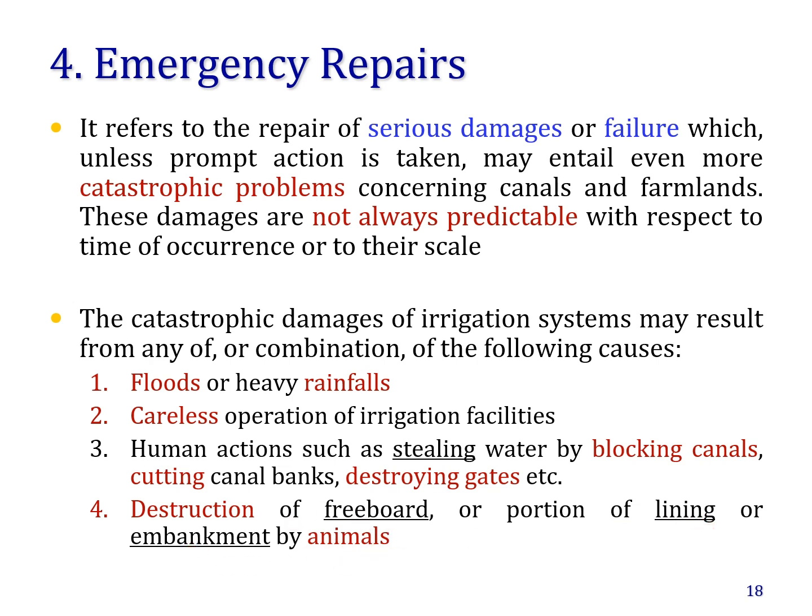That may also happen, because when too many animals enter the canal, of course the water level will rise. When you don't have freeboard, the water touches the embankments, and when the water starts touching, the embankments start getting eroded, and ultimately that can lead to breaching of the canal.